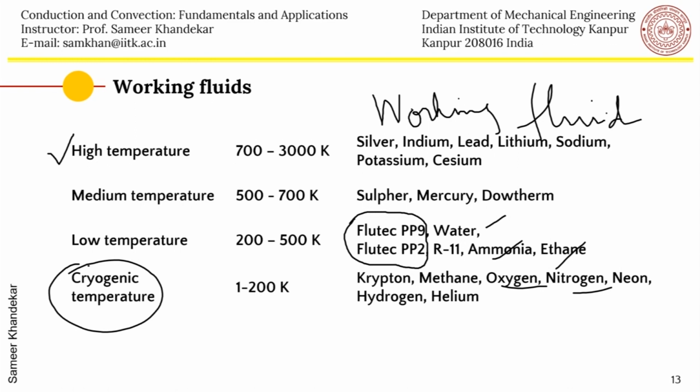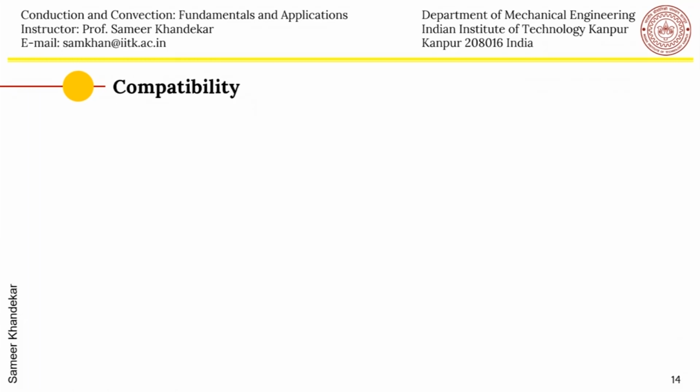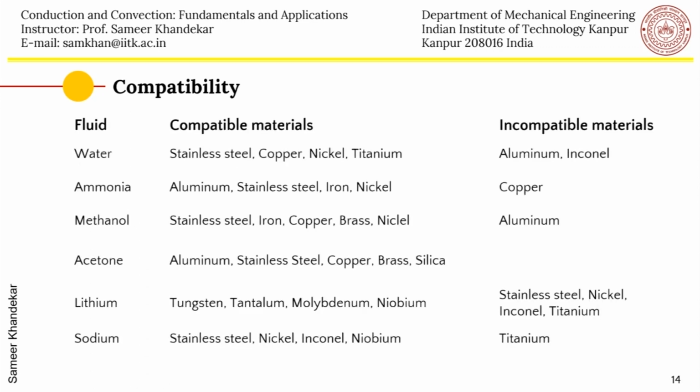porous wick. And we want the active life of a heat pipe to be, let's say, 10 to 12 years. In a space application, for example, a satellite may require a life of 7 years or 12 years. Space vehicles may require longer periods of time. And even for terrestrial applications, for example, solar heating or electronics cooling, laptop cooling, the typical life may be 5 to 7 years. And during this time, the idea is that this fluid should not react with the porous material and form some gases which are harmful for the heat transfer to take place.